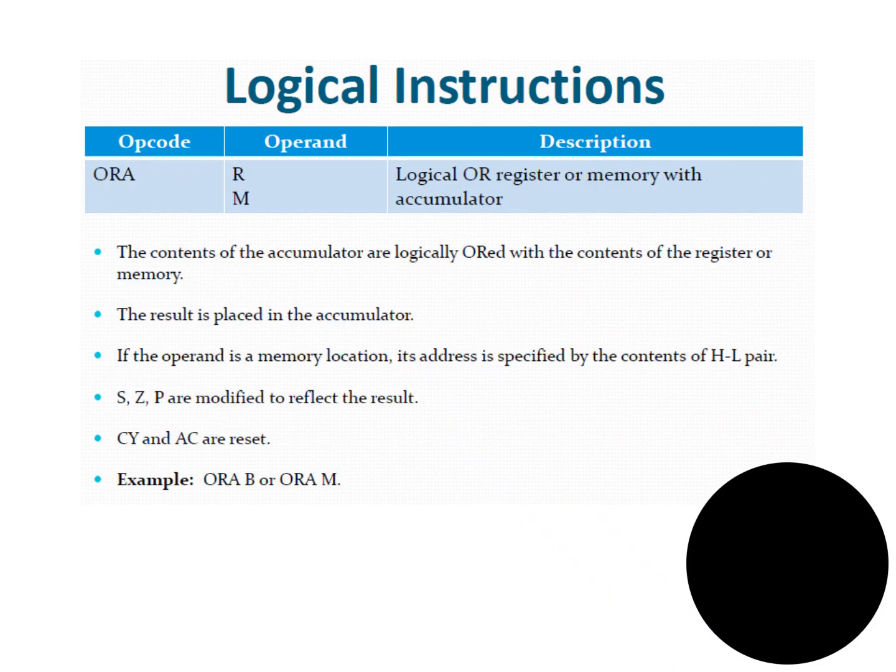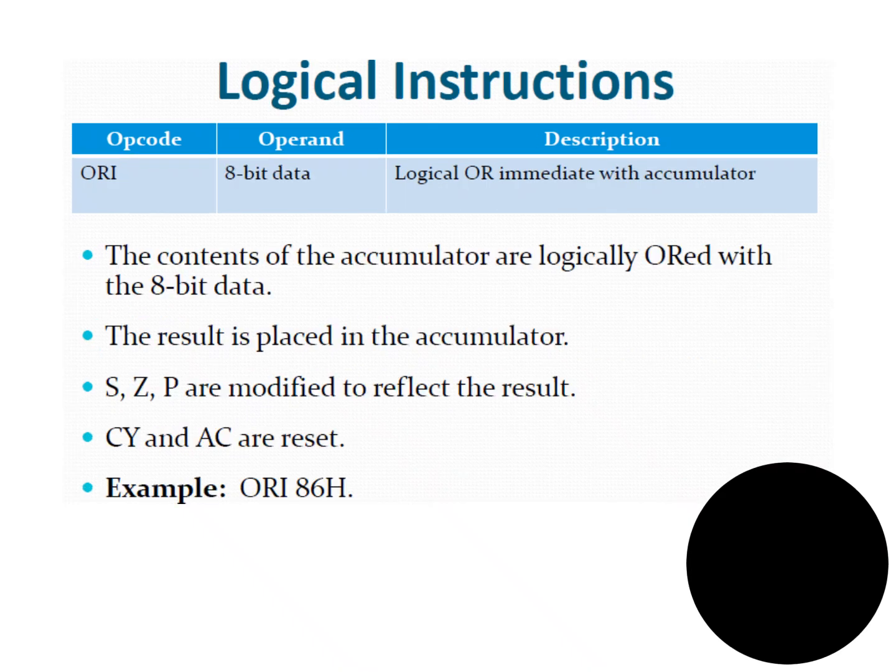OR operation means ORA B. Okay, so for any arithmetic and logical operation, one of the operands should lie in the accumulator. So this is how it is processed. ORI is nothing but OR with the immediate value which is mentioned in the instruction.